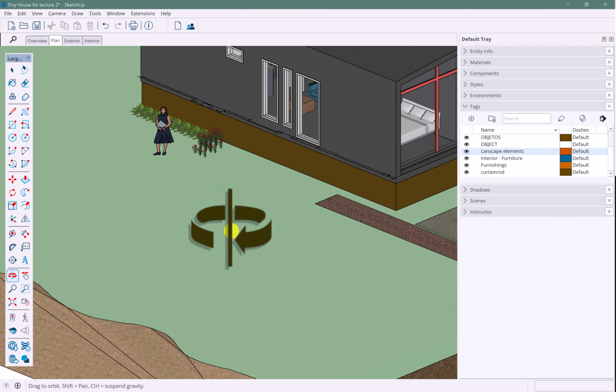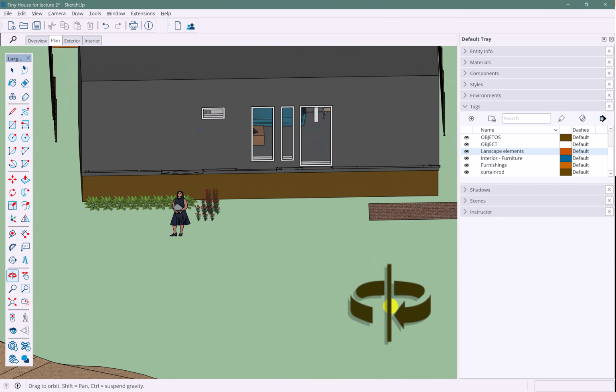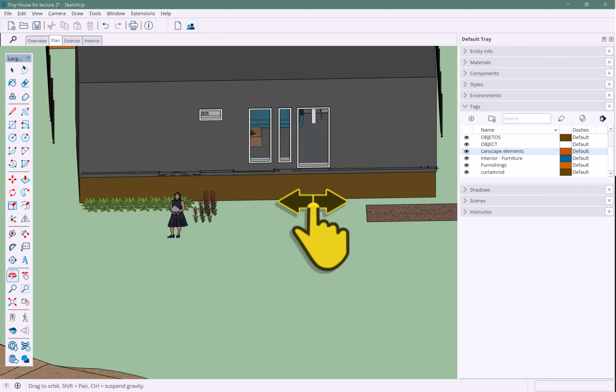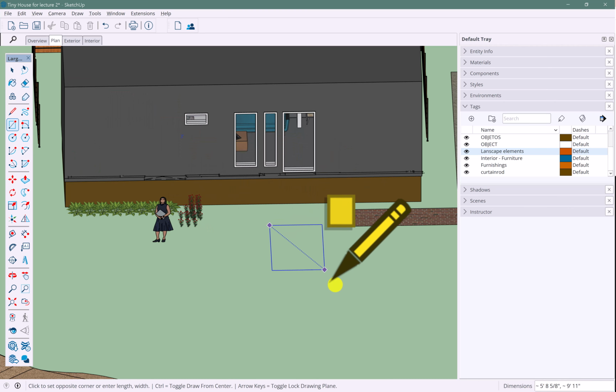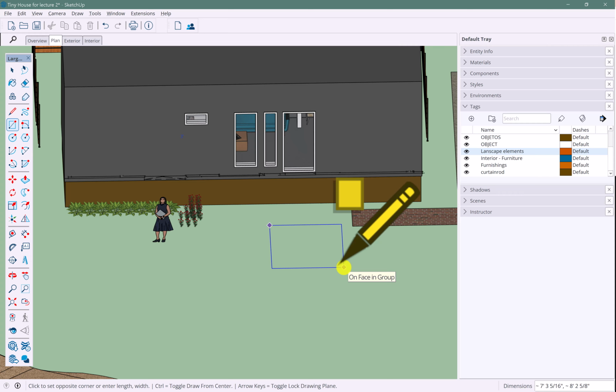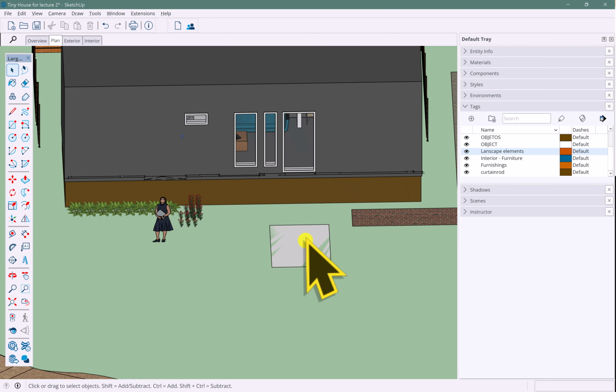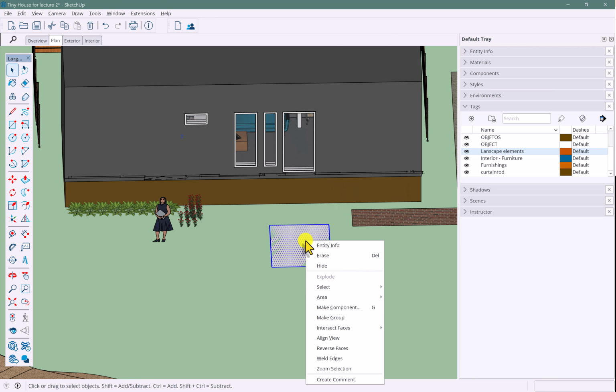Something I'm probably not going to find in the 3D warehouse is some front steps for my project. Those tend to be kind of custom objects, and what you can do, you can just make them yourself. And I'll just draw a landing here, and I don't know, maybe it's 6 feet by 8 feet, something like that. Just be sure, like before, that you make it a group.